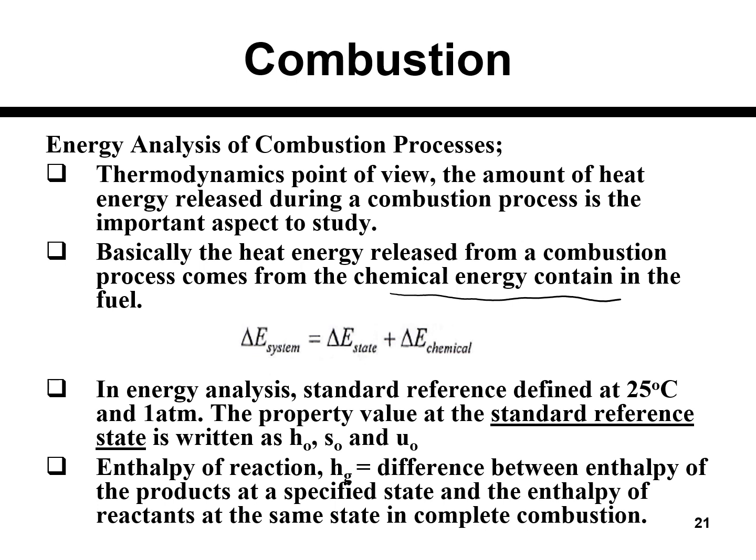So in energy analysis, we're going to use a standard reference at 25 degrees Celsius at 1 atmosphere. The property values at the standard reference state are referred to as H0, S0 and U0. The enthalpy of reaction is the difference between the enthalpy of the product at the specified state and the enthalpy of the reactant at the same state in a complete combustion.